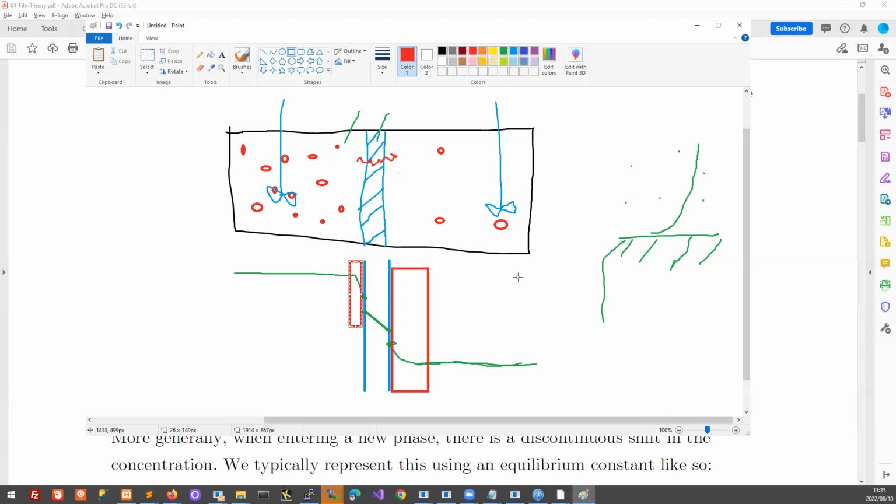By film, we can think of it as the region where most of the concentration difference resides. If you look further in, you can see the concentration is not changing much. So we'd rather just lump everything here. We don't want to think about concentration variations where there are none. So we want to say all the concentration difference on the cell on the right is in this red box here. Similarly on the left, there's no real difference across here. All the difference is concentrated in this zone.